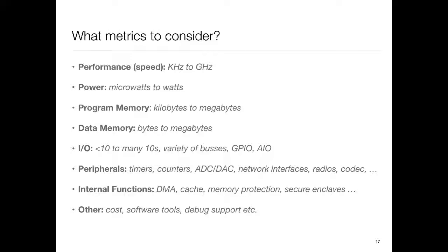In the MCUs, it's much flatter. Usually instruction caches are not there, or maybe there is one level of caching, and the program resides on the flash memory on chip. So very typically these MCUs are designed so that the processor fetches the instruction from the flash and executes it. None of that 3-4 level hierarchy that is common in normal processors.